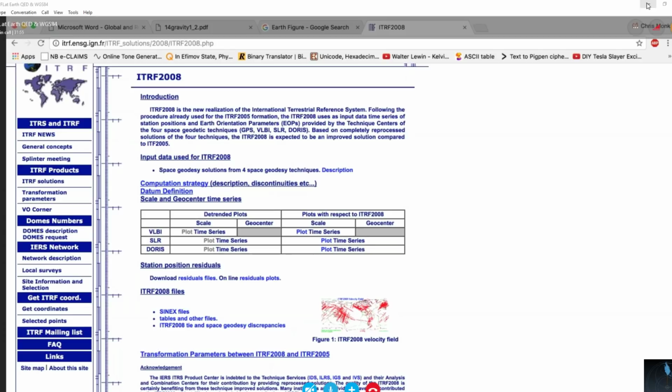Right. Okay, in one of the conversations we had, you said that if one of your surveyors under you was not to level his transit, you'd probably get sacked. So what is leveling a transit? Well, you set it on a tripod and you level it in your XY. Well, you level it on the X-axis, make sure it's level on that X-axis, and level it to the Y, and make sure that the bubble remains centered with the zenith, right? And that's leveled in 3 planes.